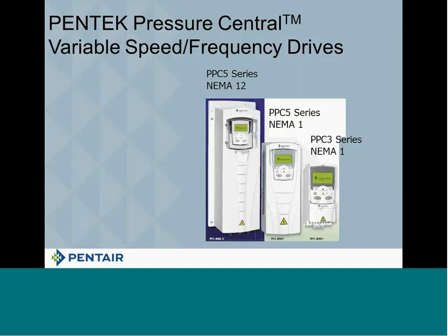Now, when you look at the PPC drives, you see the PPC5 there, it says NEMA 12, and then it says PPC5 in the middle, NEMA 1, and the last one says PPC3. They look very similar. There are some differences in them. When you talk about NEMA 1, you're going to see these slots in the side of the drive.